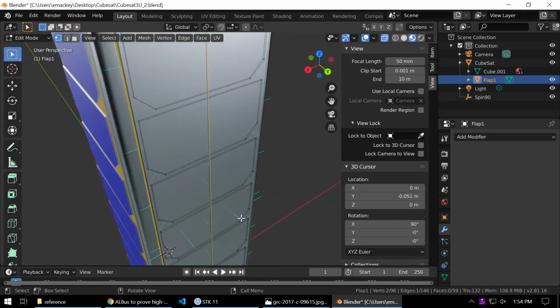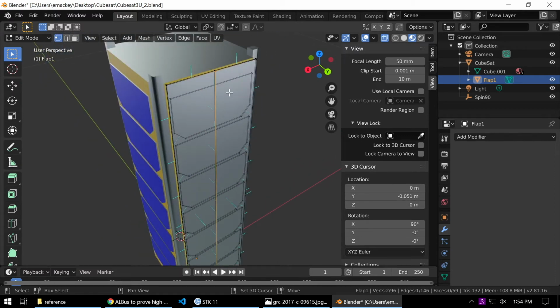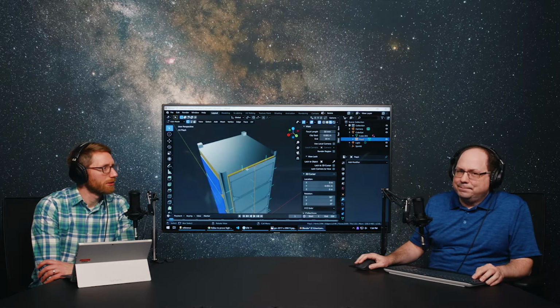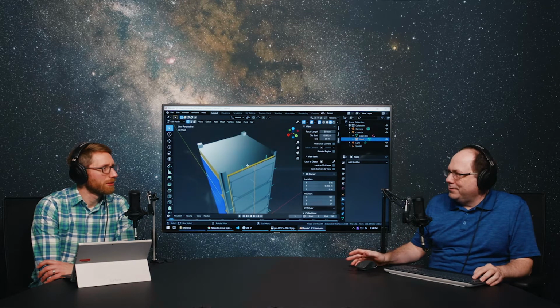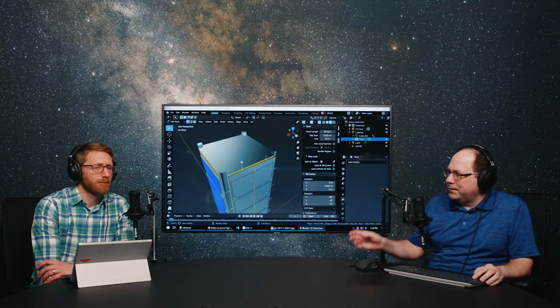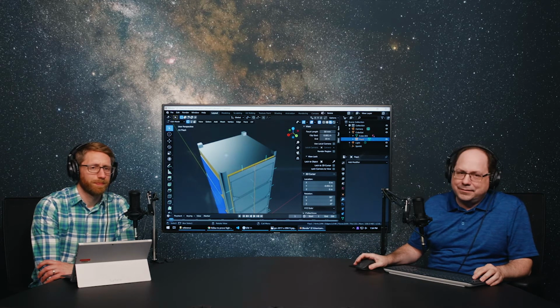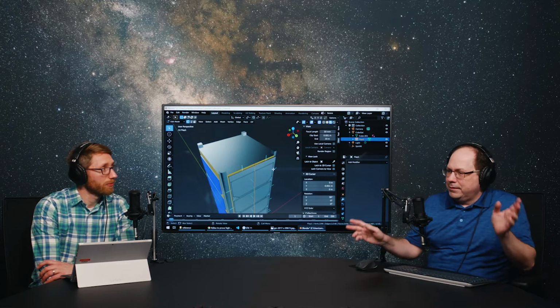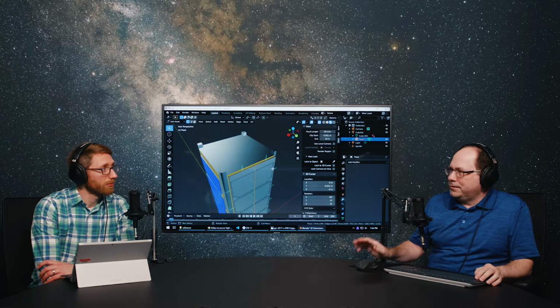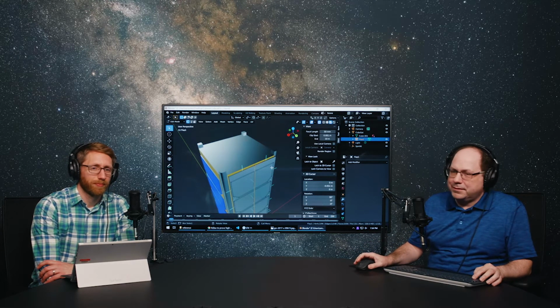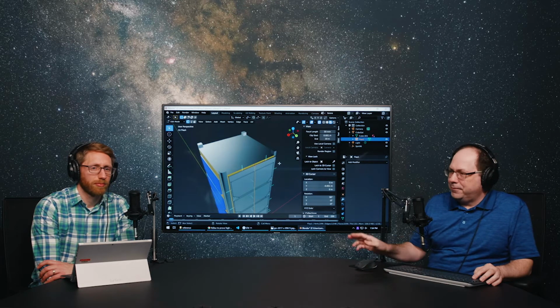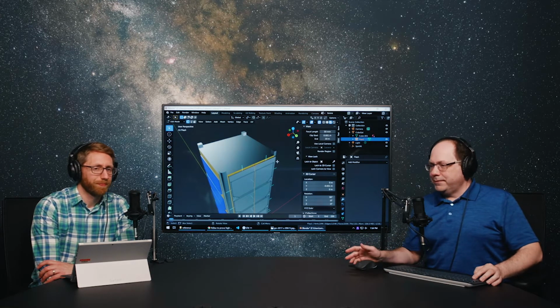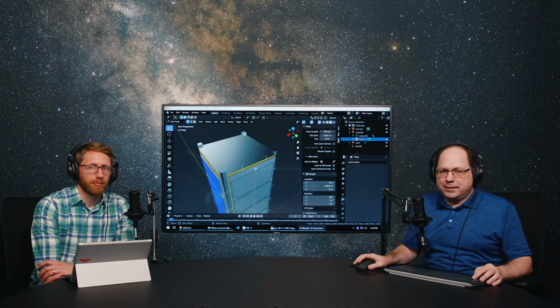Now, what's the purpose of having 2 polygons there? Just because the other ones have that same shape. The ones facing outward have that vertical split down the middle. It's kind of an artifact from when we did our array modifier. But I didn't want the back of this to be sort of a 6 vertex n-gon for no reason and have the triangulator mess it up later. So I just put a slice down the middle so it looks like the other ones.